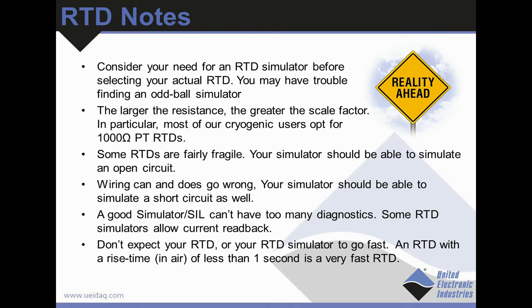So, a few RTD notes. One thing you may want to consider before you even design your RTD system is whether there is a simulator available for it. There's not a lot of RTD simulators out there. We don't make the only one, but they're few and far between. So before you design around an oddball RTD, a nickel or a copper or even a platinum that's an oddball resistance, make sure you can find a way to simulate it if you need to use a SIL or build it into a simulator.